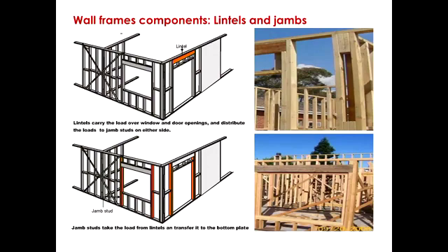So these two elements together allow you to create an opening in the stud wall, but by puncturing the wall, you're creating a discontinuity, and therefore you need to make sure that the forces that are coming from the first floor are somehow transferred in another way. So the lintel is transferring those forces to the jamb studs and to the ground.